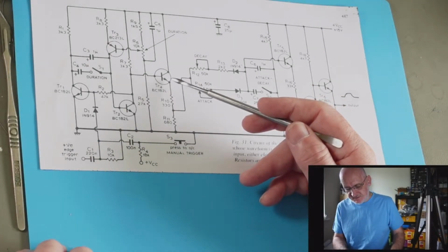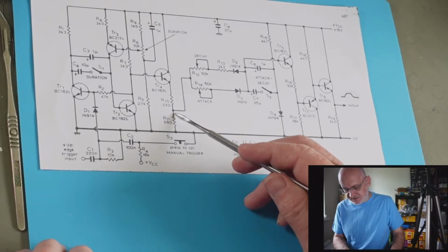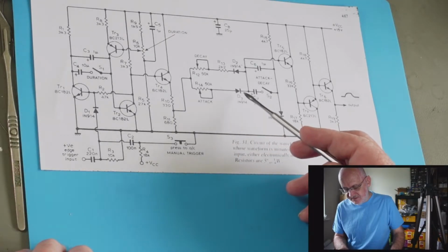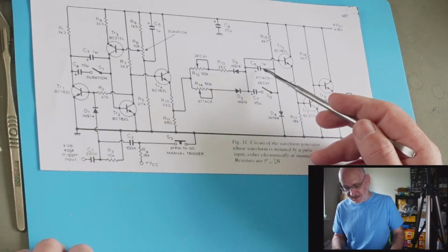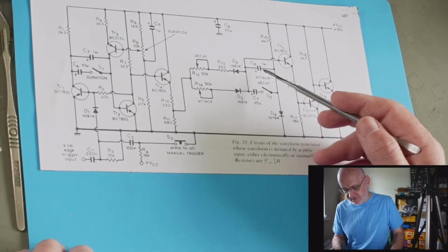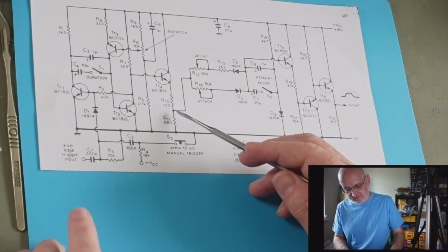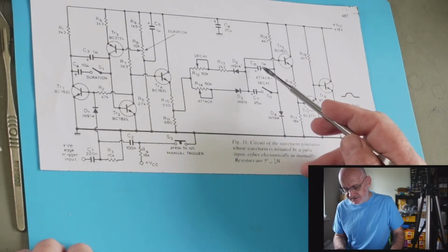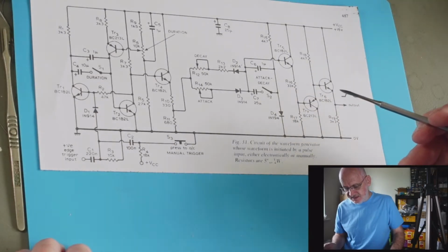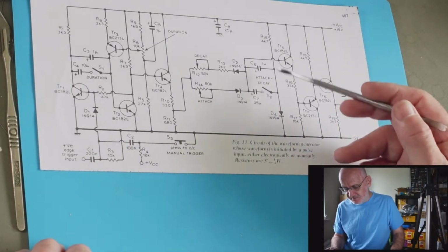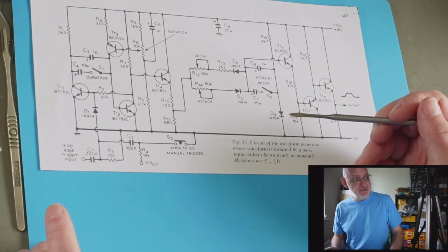TR4 acts as a buffer, and when the voltage goes high at this point, the current is then steered via D3 to charge either or both of the attack capacitors at this point. When this point goes low at the end of the monostable period, these capacitors discharge via D2. As the attack and decay are controlled by the charging of these capacitors, they are effectively exponential.